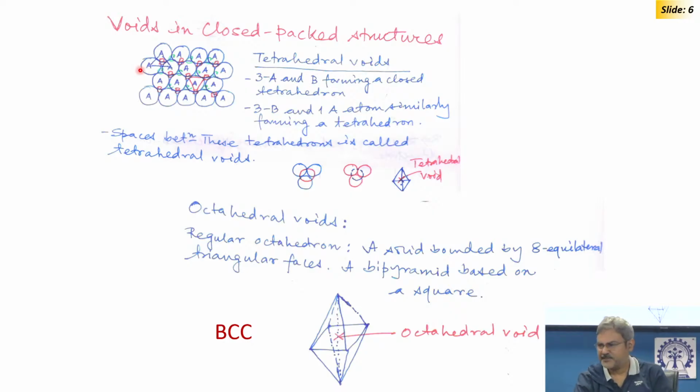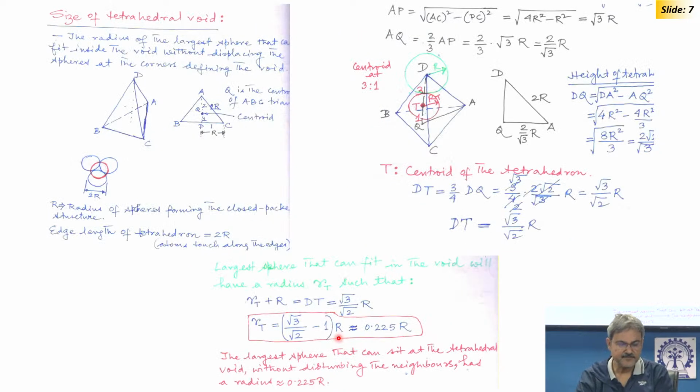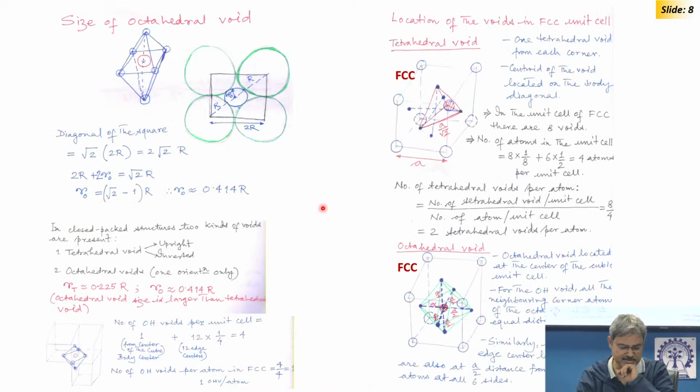So, now let me very quickly show you some slides. Carbon goes into octahedral interstitials in BCC as well as FCC. Here we are showing the octahedral interstitial site in BCC, and the same, and there can be calculations of the strain it produces.